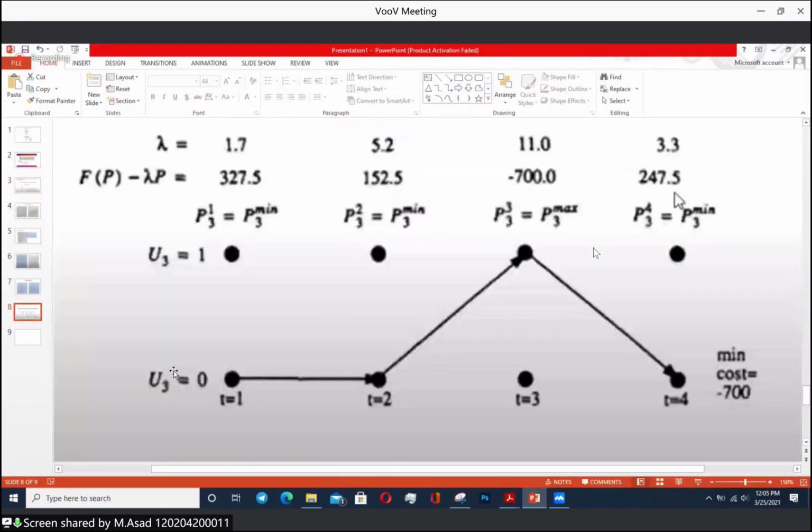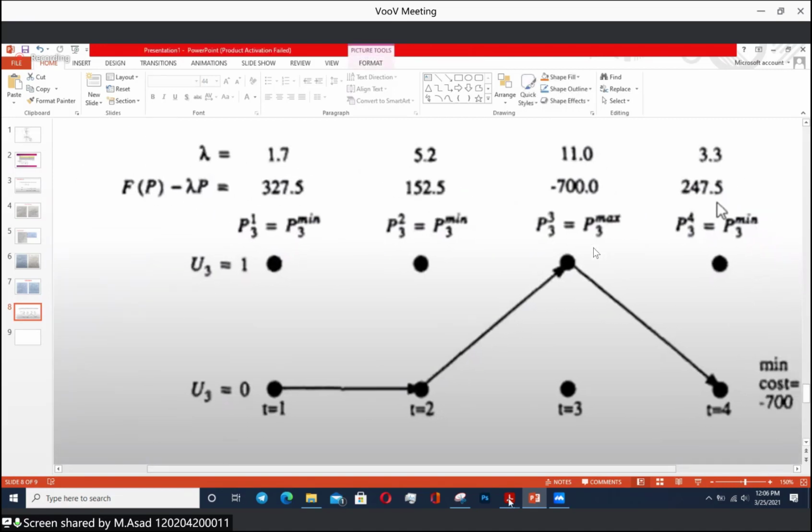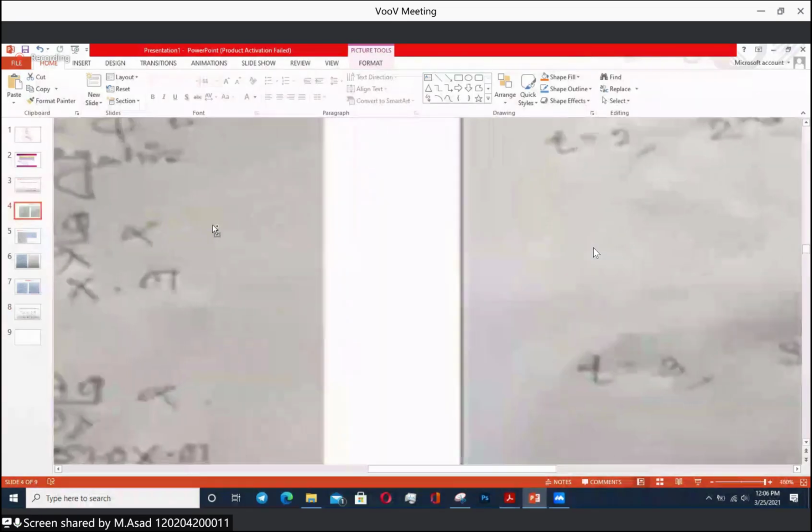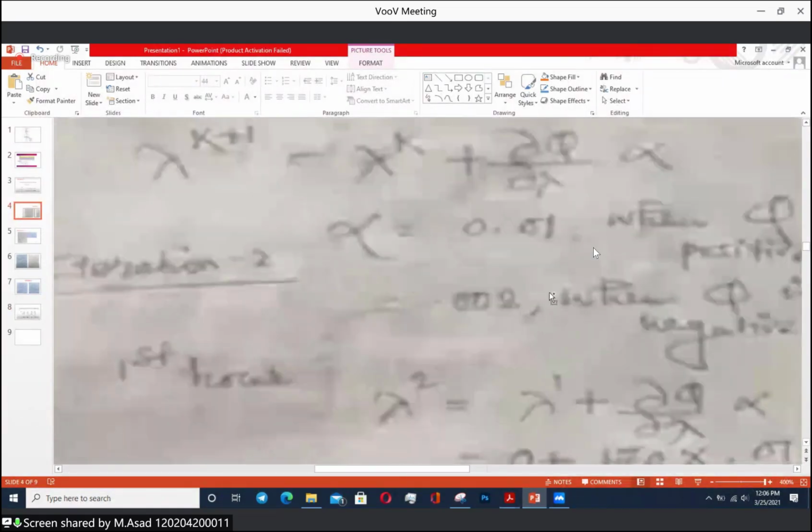in the second iteration we have our unit 3 working at the third hour, and it is at 1100 megawatt, because our third hour load is 1100 megawatt. So according to this, we need to calculate our lambda values. We will see how to calculate that. First, we need to adjust our lambda values.